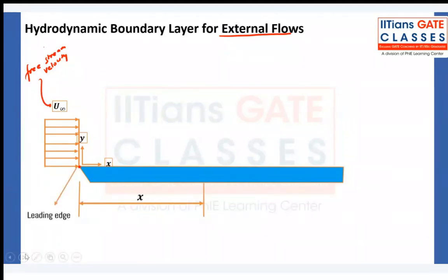Now, we are assuming we are going to a certain distance x. We have taken a certain distance x. Now what will happen? When this fluid is flowing at the surface of this flat plate, the layer of fluid in contact with the flat plate at this point will be stuck. Here velocity will be 0, or u will be 0.